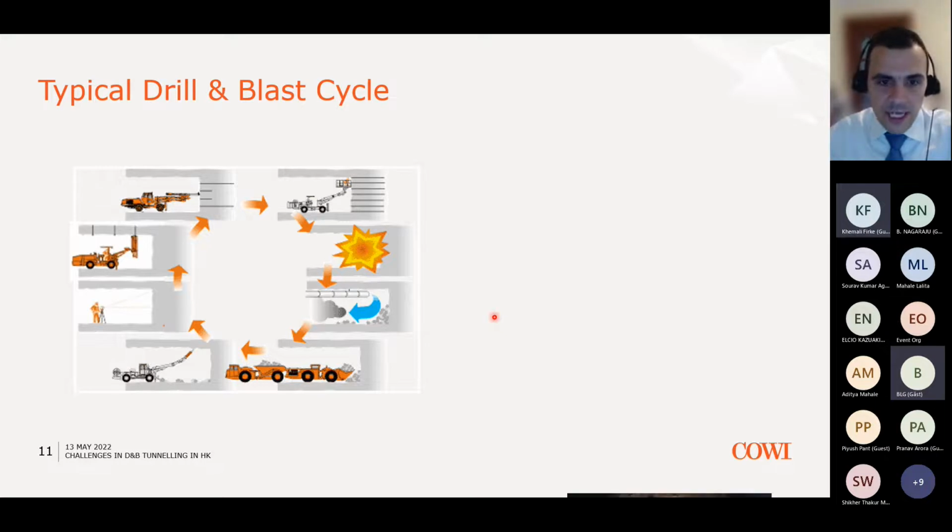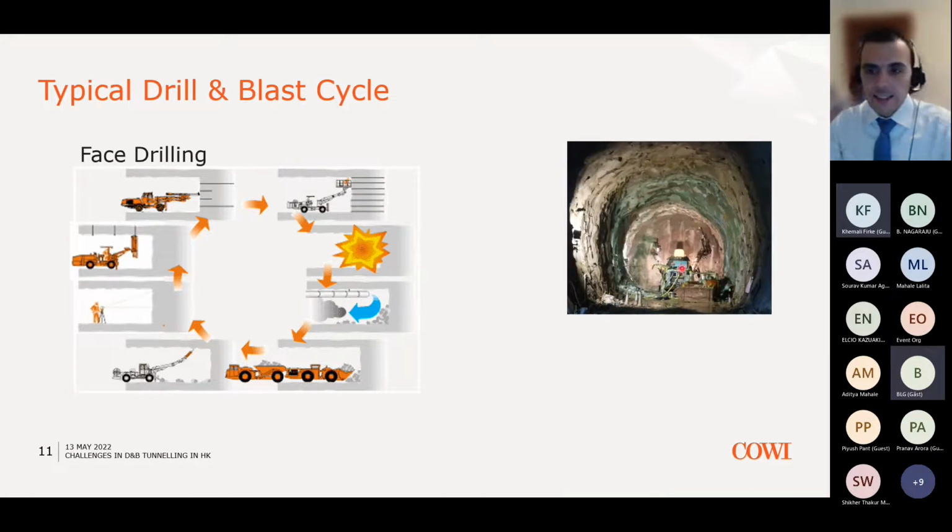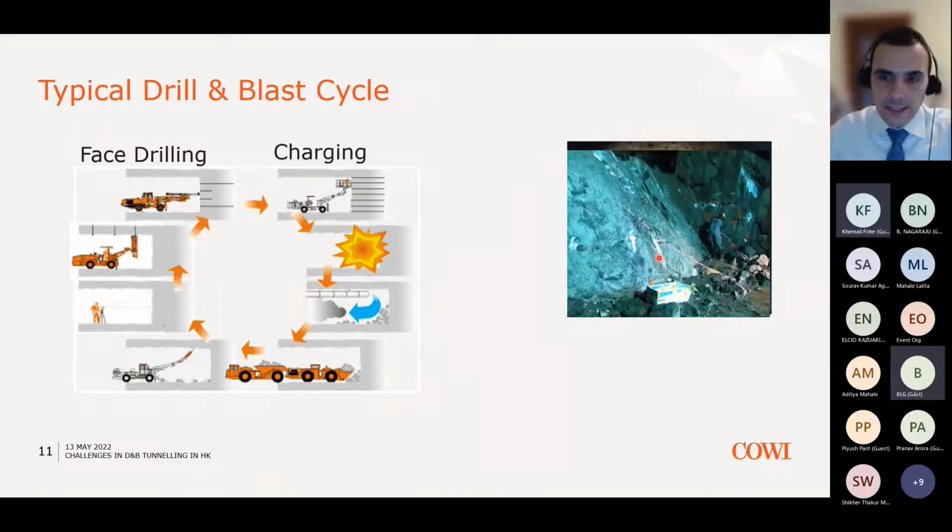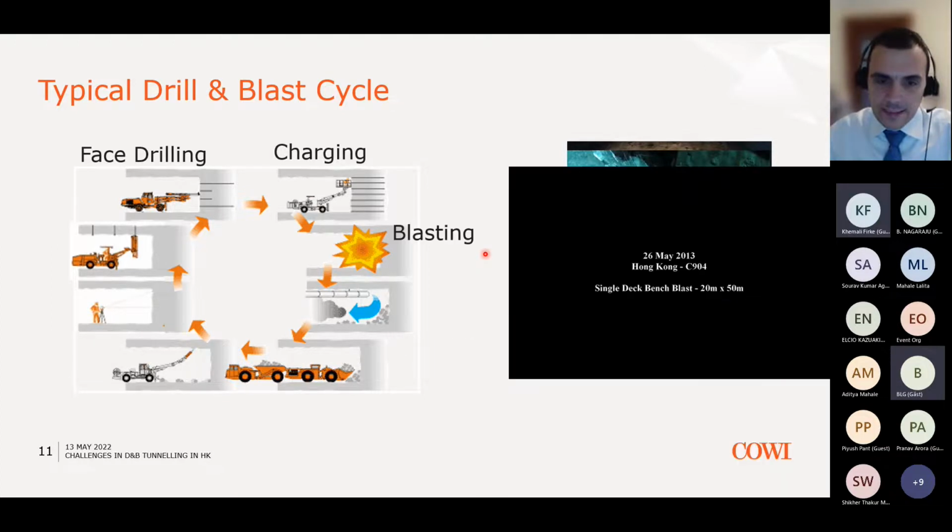So the first part of the cycle consists of drilling some holes in the face of the tunnel, so that in the next phase you put in some explosives and detonators and you charge these explosives. The next part of the cycle is the actual blasting. So I will show a very short video about that.